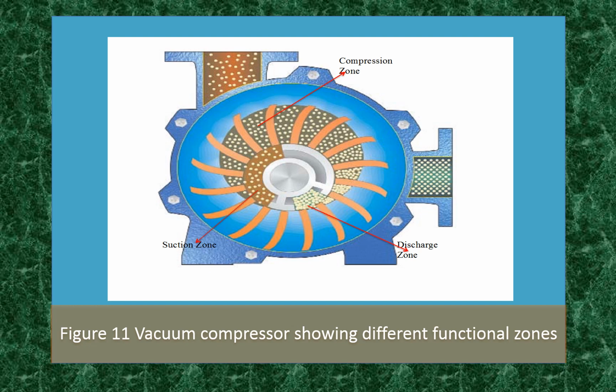A liquid ring pump has an impeller with blades attached to the center hub, located in a cylindrical body but offset from the center, that is, eccentrically mounted. When the pump starts, the impeller swings the liquid sealant by centrifugal force to the outside walls of the body, forming a ring of liquid at the outside walls of the body.